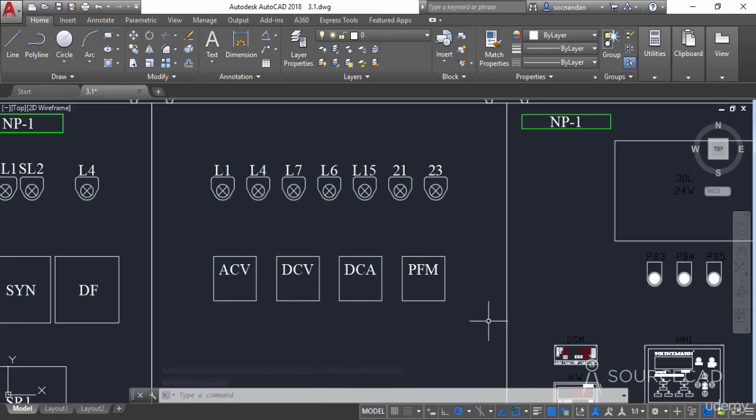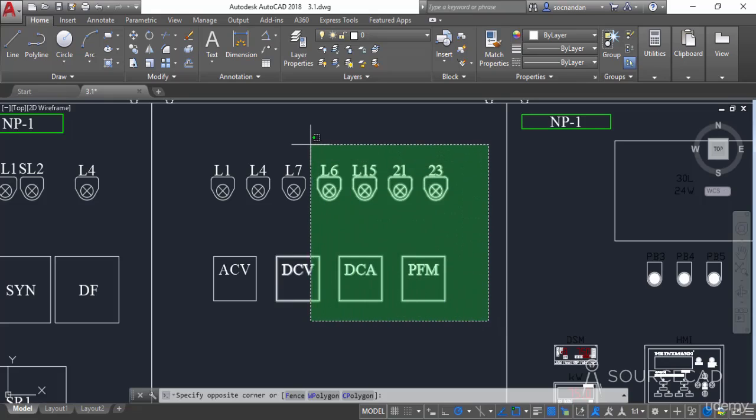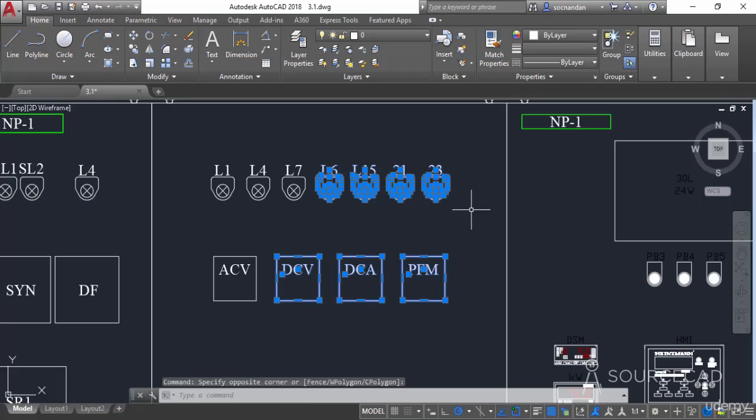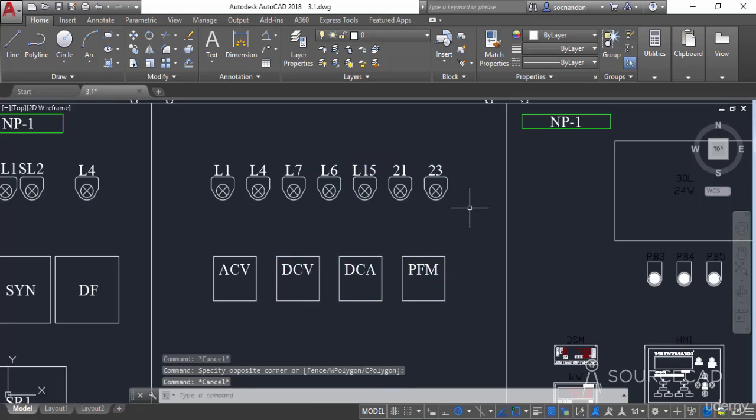Now let's repeat the process with another window. I'll click on the right side of the drawing area and move my cursor towards the left, and now we have this dashed window. In this case, everything which is completely inside this window is obviously selected, but also the objects which are touching this window are selected. This rectangle and the text here are also included in the selection set, although they are partially inside and partially outside, because they are touching the window. So this is the second way of selecting objects. You can use either of these options, and we have many other options for making selections.